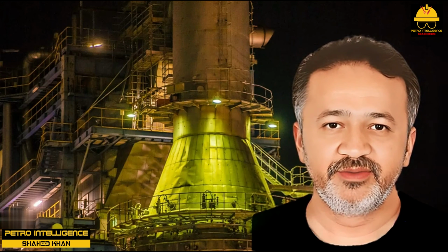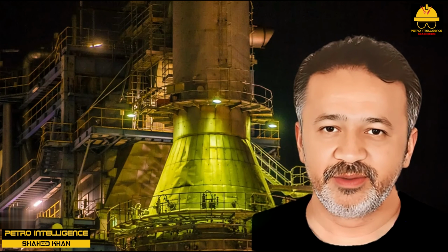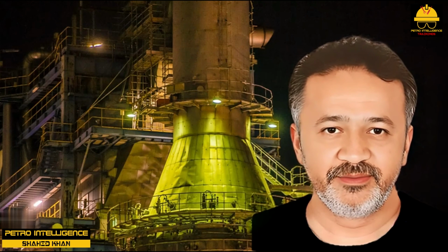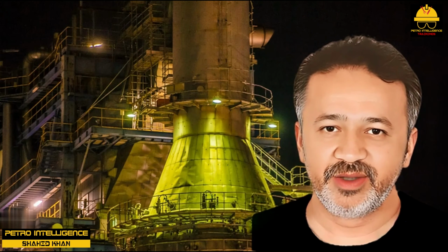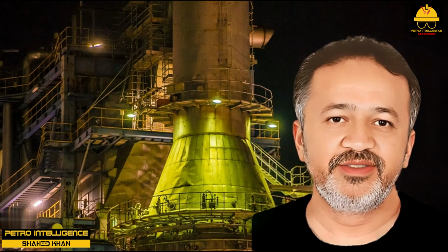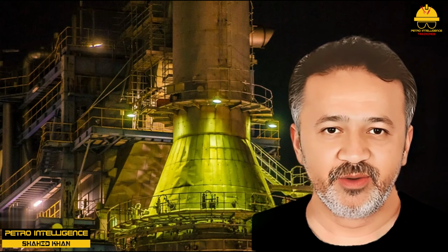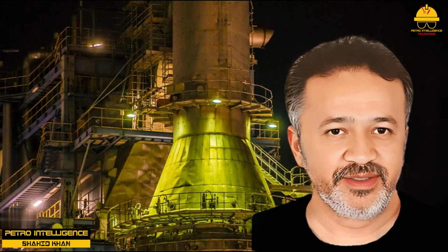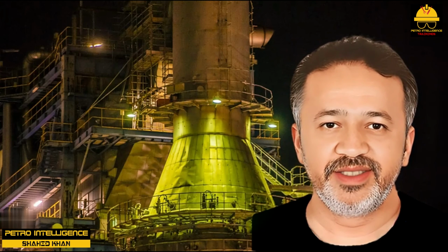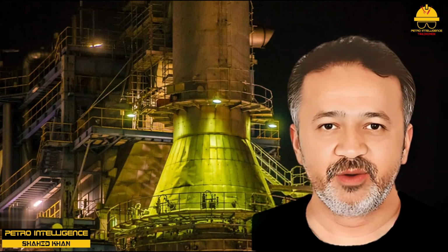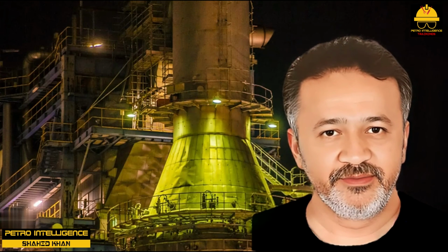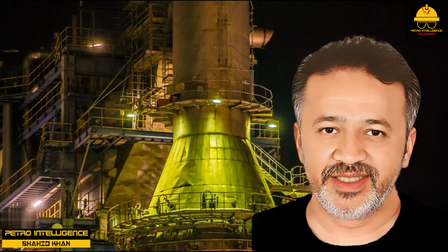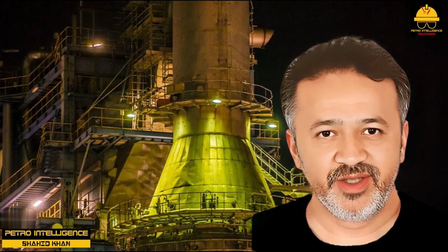An explosive mixture in the firebox is indicated for methane, that is, natural gas, when the methane content is between 5% and 15%. When the firebox methane content is below 5%, the air-fuel mixture is too lean to combust. When the methane content is above 15%, the mixture is too rich to combust. The comparable values for hydrogen are 4%, too lean, and 75%, too rich. This suggests that refinery fuel gas, which may contain 5 to 50% hydrogen, can explode much more readily than natural gas. The presence of H2 in fuel gas is a strong argument, then, for connecting pilot lights to natural gas, which is very low in H2.